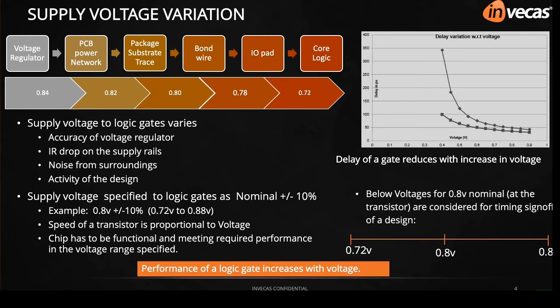Second one, the general supply network is built by using metal layers. So by default it becomes a non-zero resistance network. The resistance in the network will be less to the cells which are placed nearer to the source and more for the cells which are placed away from the source. This means that the supply voltage for the cells mainly depends on the voltage drop across the various regions of the chip. Because of this reduction in the supply voltage, the propagation delay of the cells is going to be increased, and the same needs to be taken care of when we are doing the sign-off timing analysis.